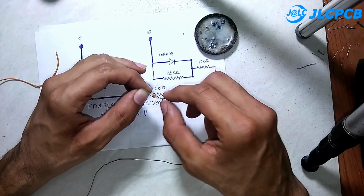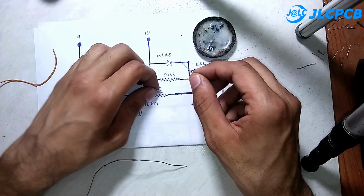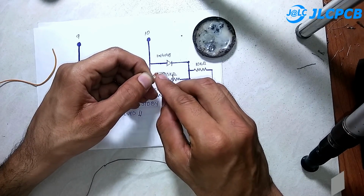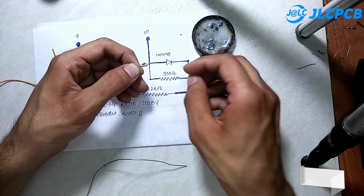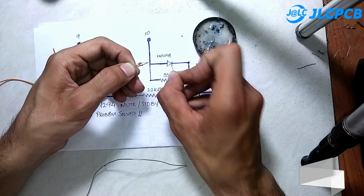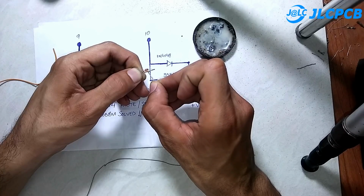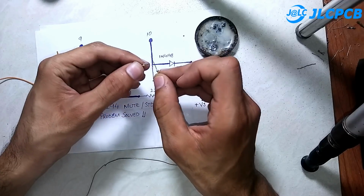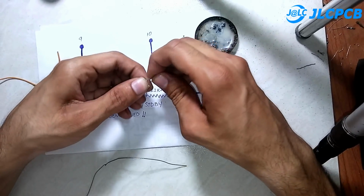So now I will take this 10 kilo ohm resistor, which is this one, and I will solder it on one side of our diode. At the cathode of this diode, you can see here that this point is the cathode, the black color side of the diode. So I will pick this 10 kilo ohm resistor and connect it here like this.